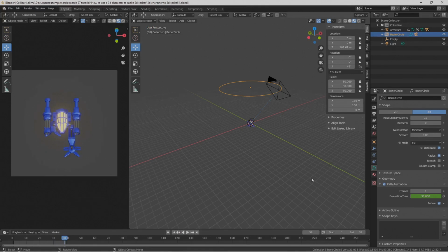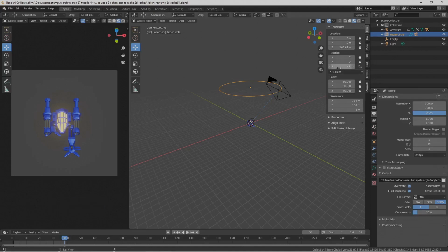Okay, what you want to do now is go to what looks like the printer. Make sure that when you're selected on the curve, this Z says 45. The reason you have this set for 45 is so you can go plus 45, plus 45, plus 45. You're plussing 45 until you get to 360 to get all of your different angles.